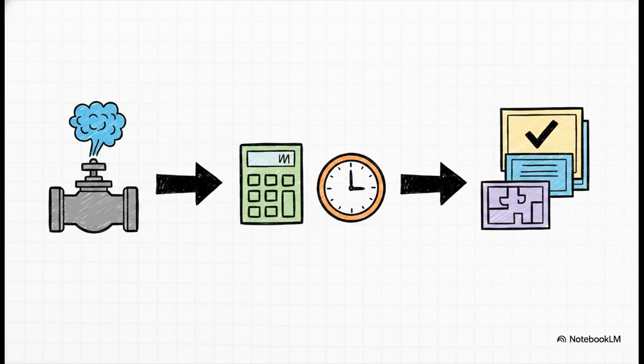Before this, you might have just been looking at a bunch of acronyms, but now, you can run the full point source method from end to end. You can find the sources of release, grade them, run the vital ventilation dilution and persistence time math, and actually compile the 3 official documents that prove the facility is safe. That is the entire logic behind every hazardous area drawing you will ever review.